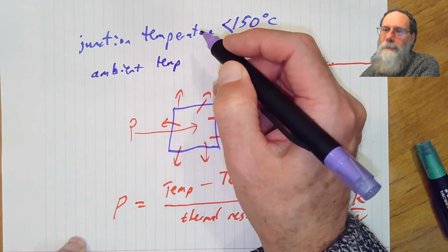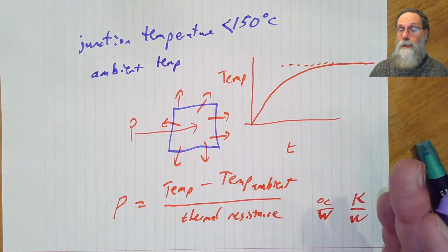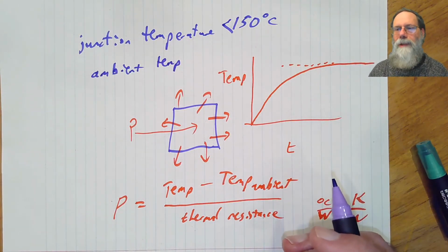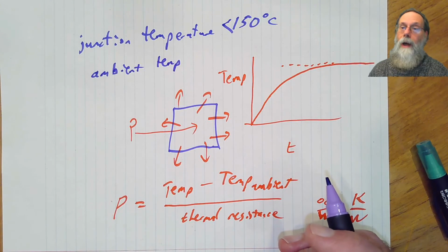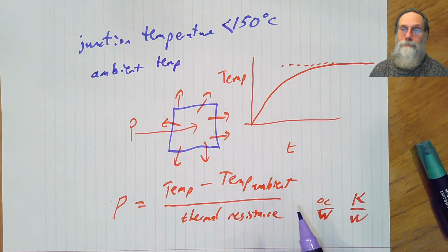And you might be tempted to say, oh, 25 degrees C, that's the room temperature. But remember that electronics devices are often inside boxes. The boxes get warm inside because you're dumping a lot of heat into them, and unless you've got a good fan blowing that warm air out again, the ambient temperature may be a good deal warmer than that.